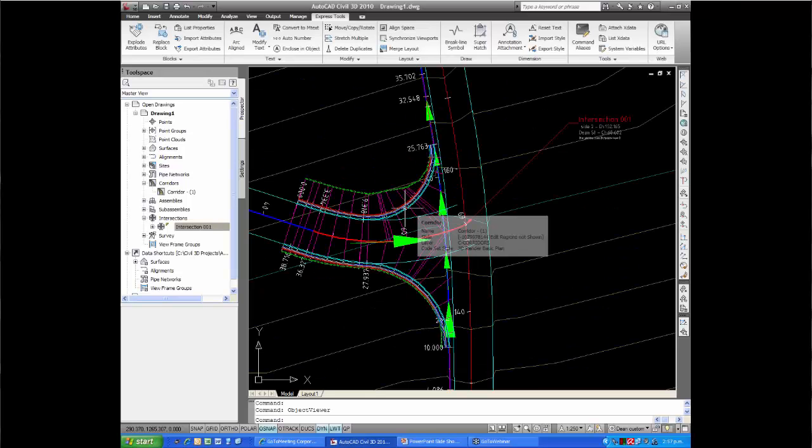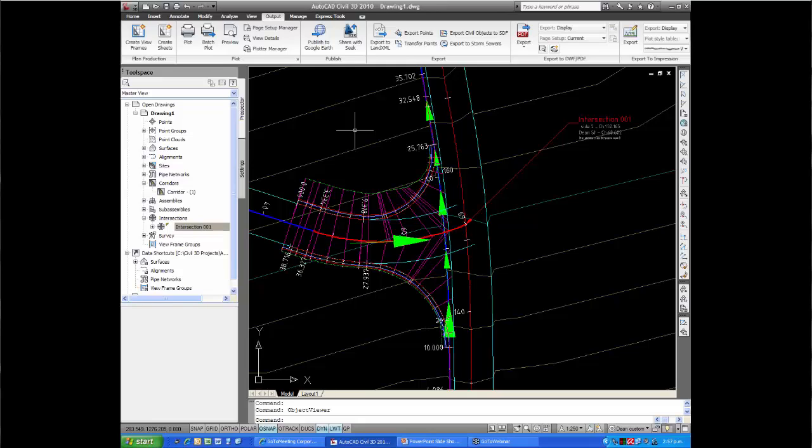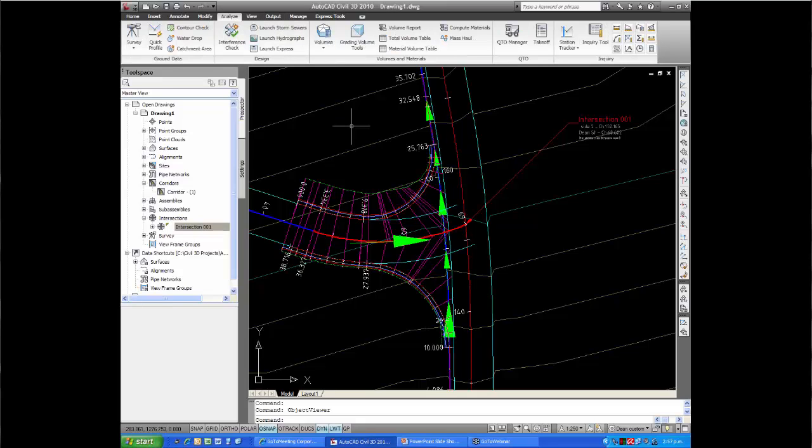What I've tended to be looking at just recently is doing it using the quantity takeoff stuff, the QTO. Let me see, it's under the Analyze tab. I can just quickly work out the total area of paved surface in there.